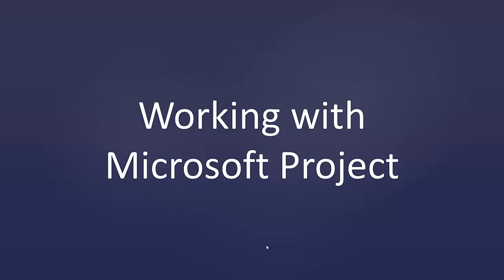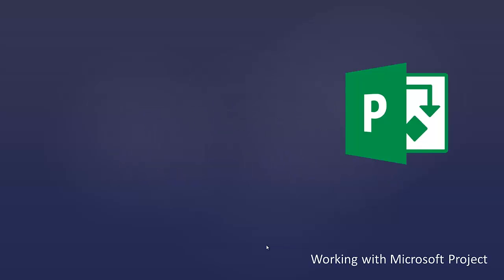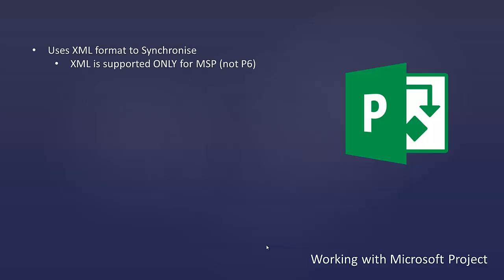So finally, some notes about working with Microsoft Project. The first thing to point out is Synchro uses an XML format to exchange data with Project, and this is only supported for Microsoft Project. I know that P6 does export an XML file, but it is formatted differently than the XML that would be exported from Project. And so it won't be imported correctly into Synchro. You may even receive a warning telling you that you can't import at all. So again, the XML is only supported for Microsoft Project, not for P6.